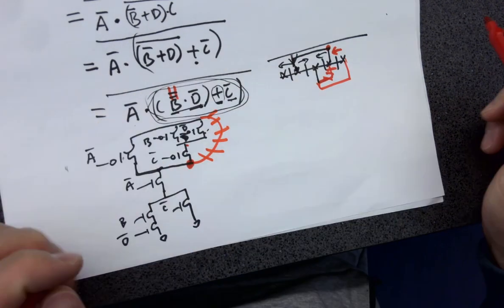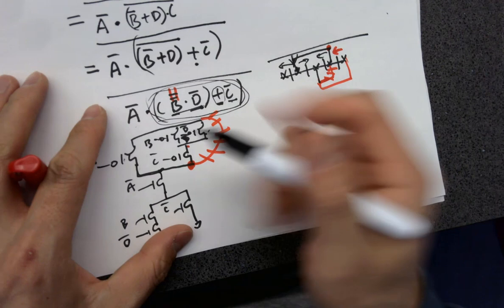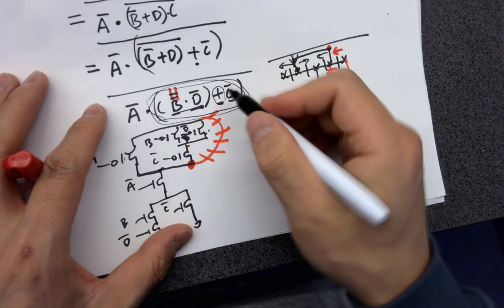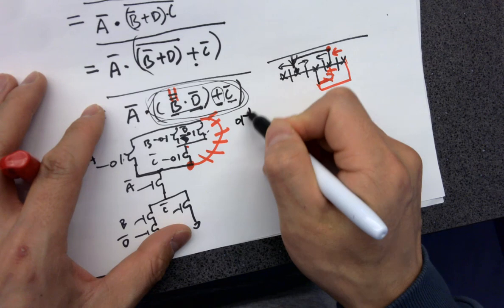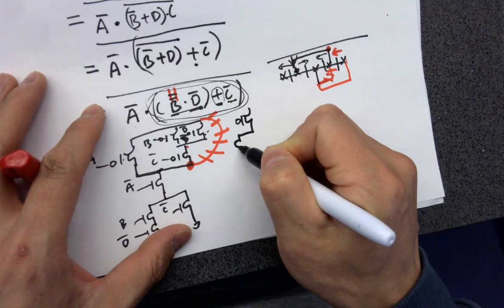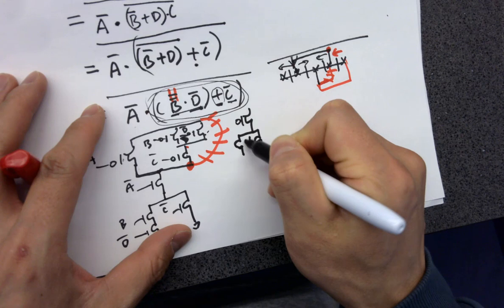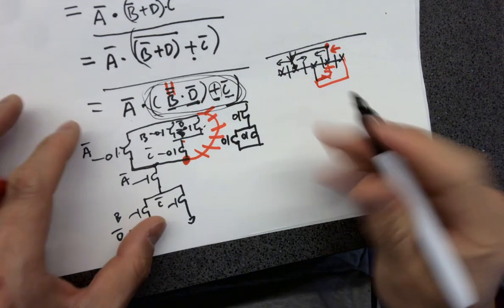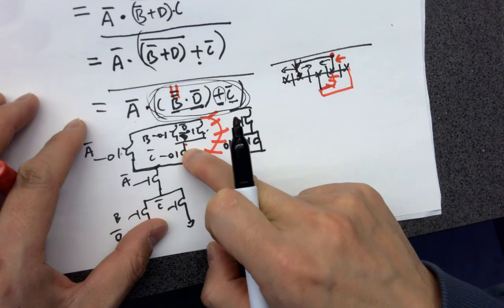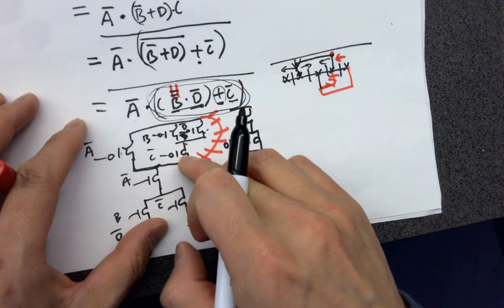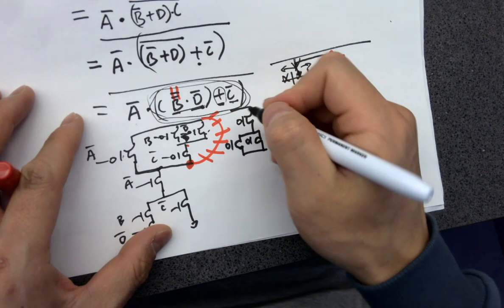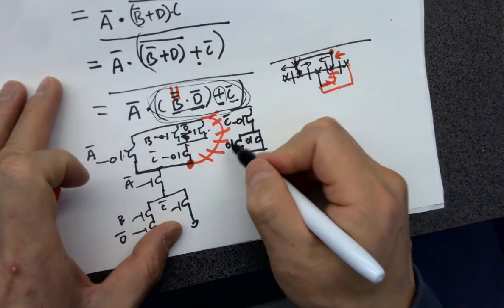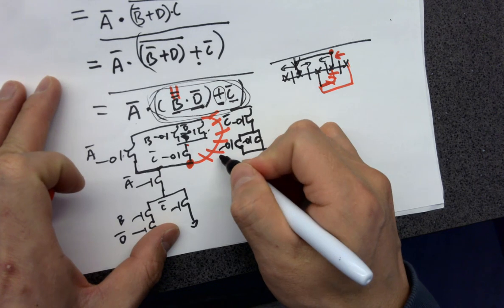How do we deal with it? Because these two are in series, and electrically, it doesn't matter if I swap it. This is still an equivalent circuit. I change this single transistor to the top and two parallel to the bottom. It's not changing anything. But you have to change your layout accordingly, so it's able to pass NCC or LVS.